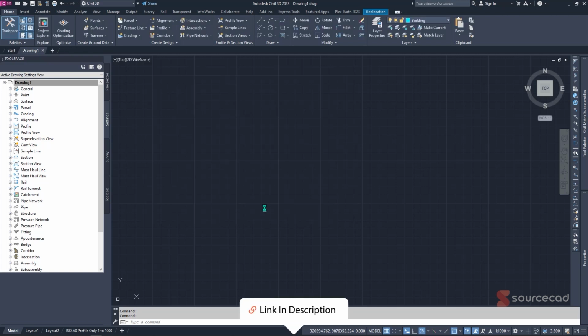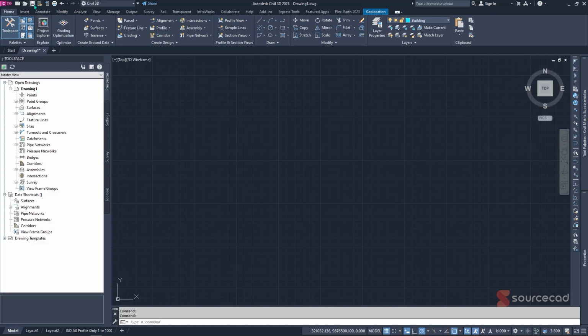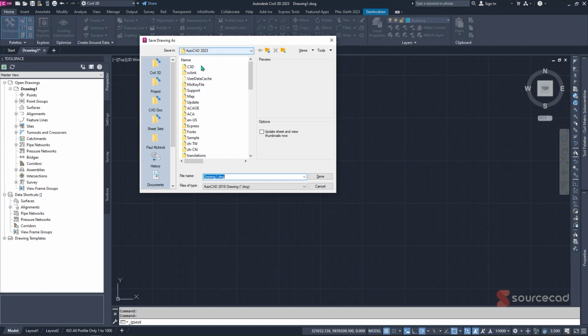So once that's done, I'll click on OK, and I will just be saving this specific drawing before I do any importation. So I'll just simply go back to Prospector. I'll click on save. So I'll navigate to the folder at which I have my documents. So in this case, I want to save them here. So documents, and I'll create a new folder called Civil 3D. And in this case, the name will be Topo map. And the drawing is this 2018 version.